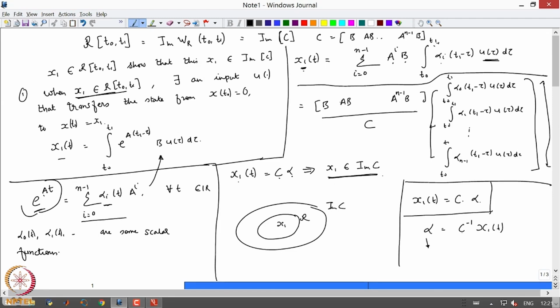So, this C, which is a controllability matrix, for a solution to hold here, the C matrix should be invertible. This is a little interpretation when k equals 1; for higher cases it may have a different interpretation, but all the undergrad texts on control will start with deriving the Kalman rank condition of this form. When the inputs are just scalars, just u is in R, I can interpret this as a solution to a linear equation, which is possible if and only if C is invertible.